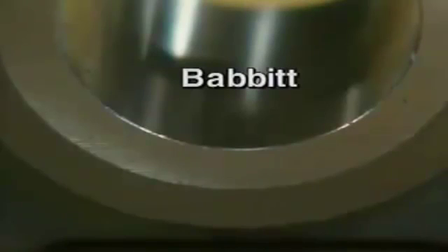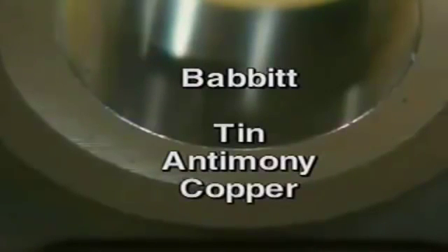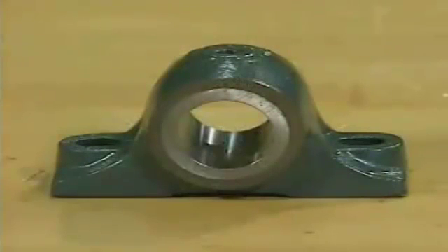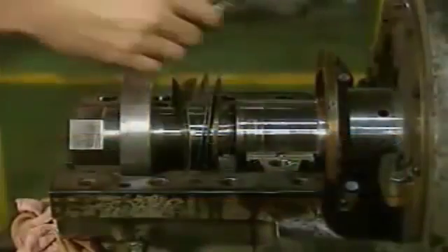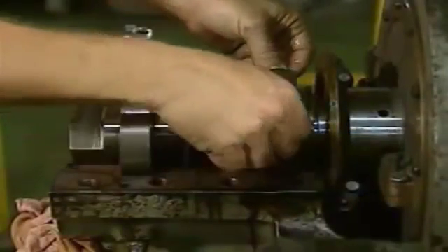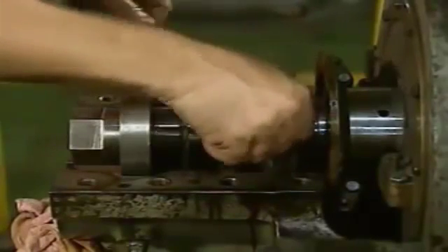The material that is most commonly used to make sliding surface bearings is Babbitt. Babbitt is an alloy made of three metals, tin, antimony, and copper. The actual amount of each metal that is put into the material varies according to the way that the bearing is to be used. Babbitt is relatively soft, so it is always bonded to a shell that is made of a stronger metal, such as iron or steel, if it is intended to support a heavy load. Babbitt is a very useful bearing material because it has all of the properties that a bearing material should have.